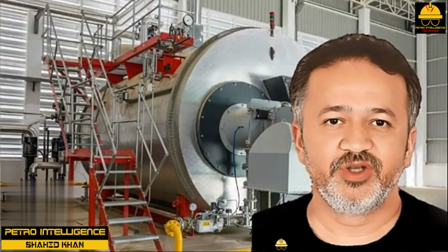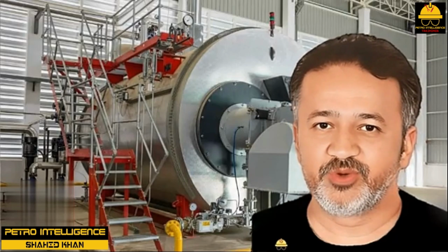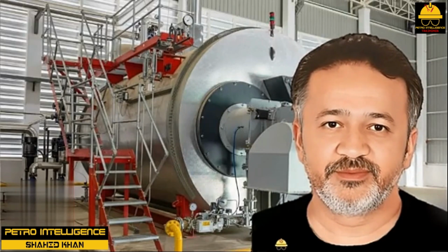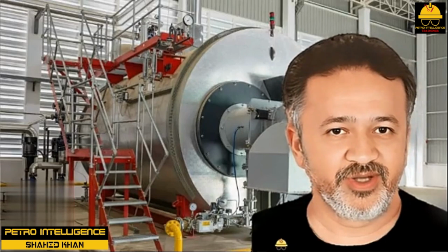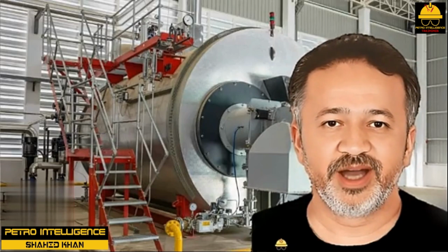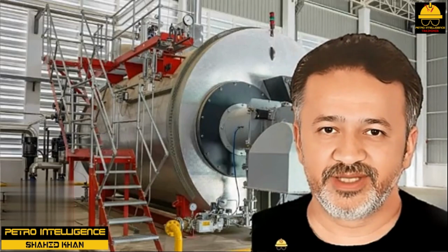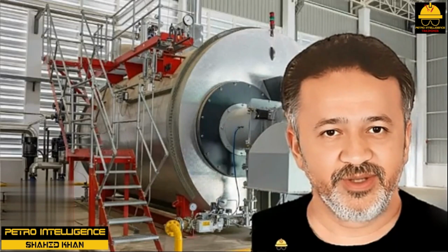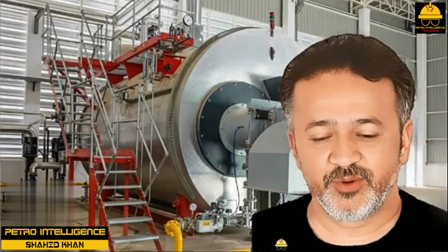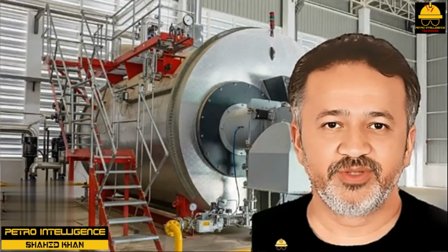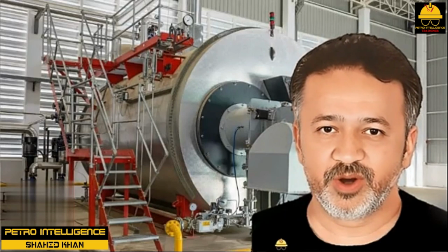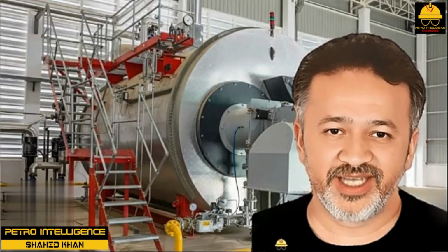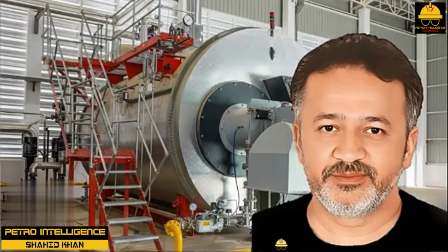Some plants collect all their contaminated steam condensate streams from reflux drums and from a vacuum tower hot well system. Without even steam stripping, the collected condensate is recycled back to the steam boiler. It's true only where low pressure, 100 psig, steam is generated. It's true the steam so generated is not used in a turbine or in any chemical process. But on the other hand, they have been doing this for 20 years without any ill effects.